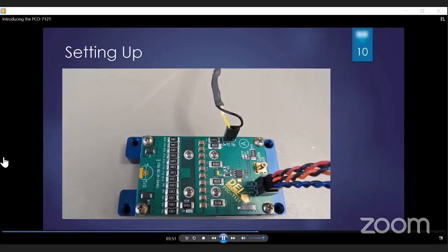So connecting up the instrument. J1 has all our control signals. Everything's color coded. So if you notice, red goes to where it's showing the trigger on the silk screen of the board. Orange is going to where it says positive 15, and blue is going to the high voltage. So we'll see those connected in the next slide.